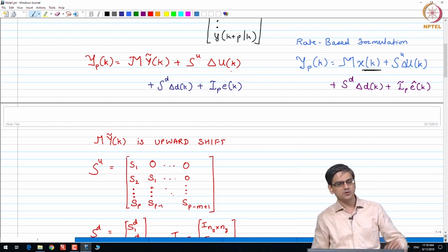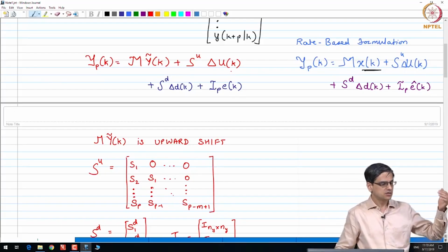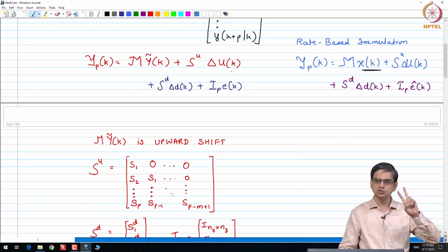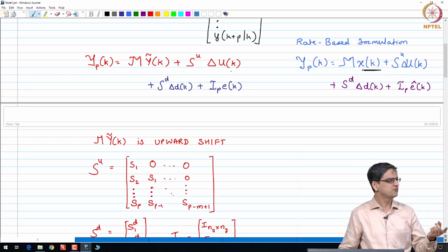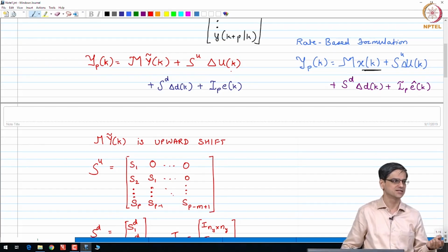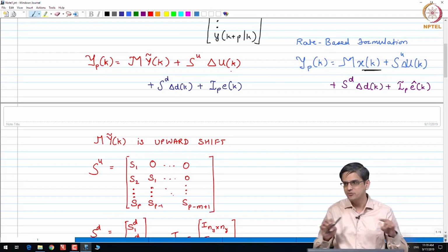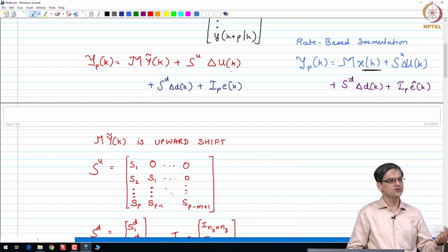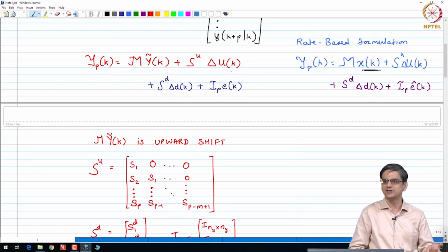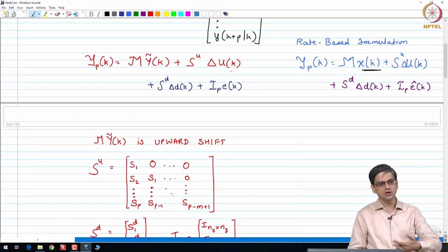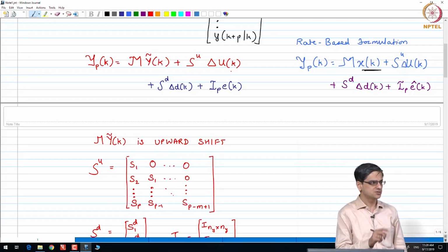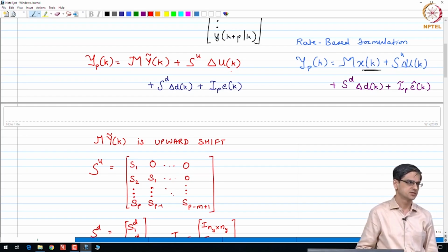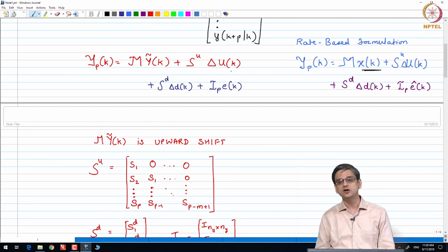If you look at my code that I have uploaded, U_k equal to U_{k-1} plus delta U is used only for two reasons. One is that finally we want to plot what U looks like, and delta U may not make sense to anyone except experts who have worked with that system. So, that is why we need to extract U. If you do not have constraints, the only reason for calculating U was to plot. It is not really used in industrial MPC. The only other place where it is used is because you have input constraints. So, you need U_{k-1} in order to get that input constraint. Otherwise, you do not even need to worry about U. Good question. No, I did not say delta D as constant.